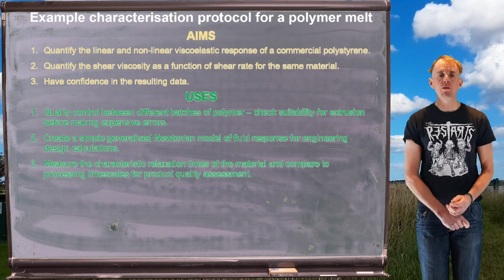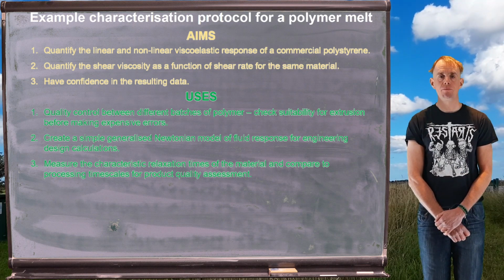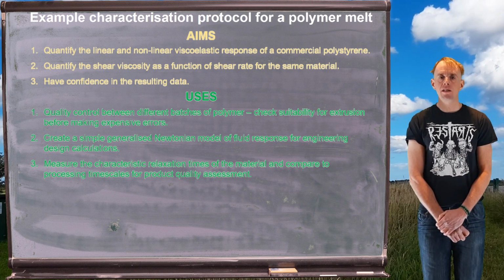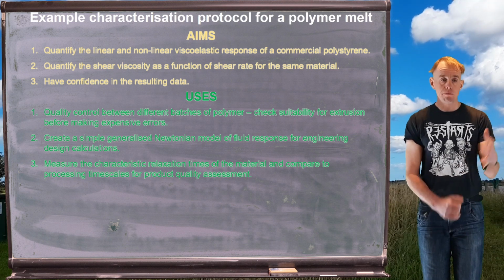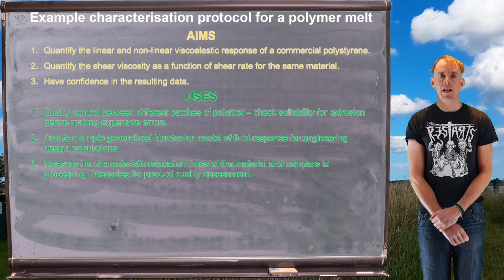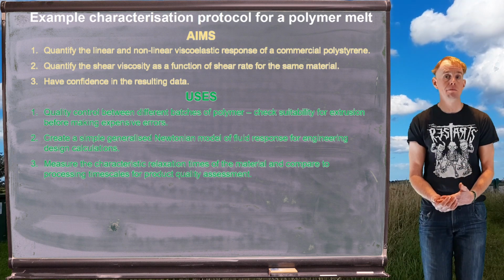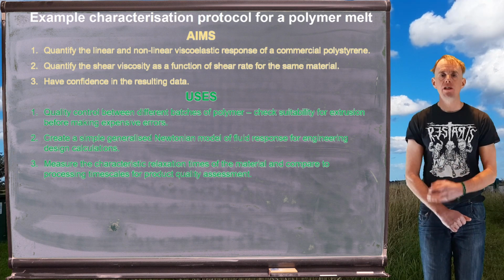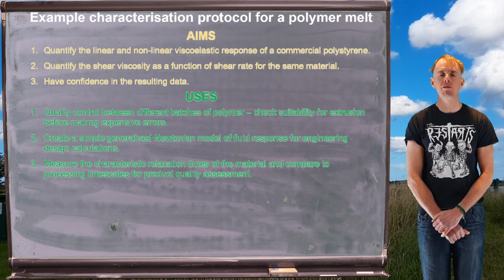So we might also want to do some quantification of relaxation time. Now, again, let's put this in the context of a solid example. Let's stick with the cast film line. You're making a cast polymer film, and a short while after the material is extruded from the die, you're cooling it using maybe chilled rollers or something of that nature, or maybe an air quench. So, how much stress is locked into that polymer once it's set, once you've chilled it, once you've solidified it?